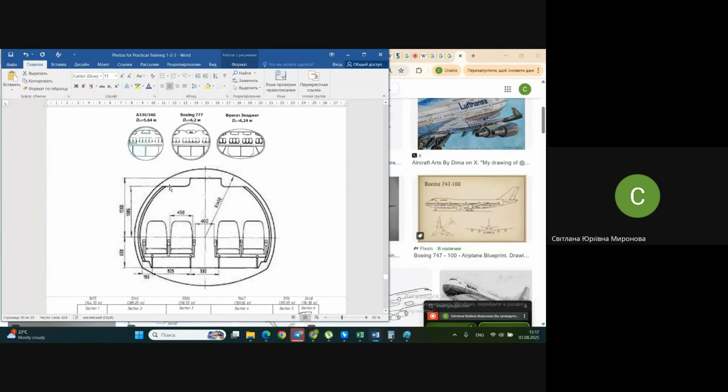High wing, low wing, whatsoever, where to place engines. Engines for passenger aircraft can't be immediately in the fuselage. Quite clear that in the fuselage you have people, you have passenger cabin, and you are rather limited in positioning of engines. Either you may place them below the wing or above the wing or somewhere at the aft fuselage. All the variants we have already considered.